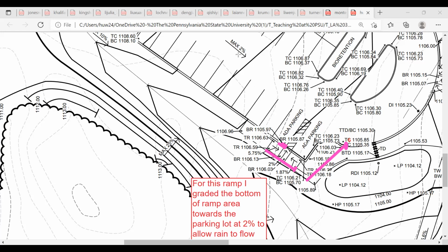So basically, originally there is a contour that runs along this face of the curb, that portion becomes here. And we need to find out wherever it's crossing that, and then connect it back to the wall and keep going. There's a portion on this one too, right? So that's how we grade this ramp. And essentially, we just need to find out wherever 6 is on this ramp.